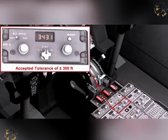However, when reduced separation between aircraft is in force, the tolerance of the equipment is plus or minus 200 feet. To verify this accuracy, a controller will, upon initial contact, verify this, and if unable to do so, inform the aircraft to switch this Mode Charlie element of its equipment off.